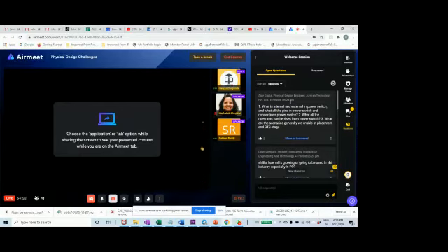So, what are the internal and external power switches, and what are all the pins in a power switch and the connections of the power switch? That is the first part of the question. Okay, let me talk about internal and external power switches. You can have a power supply switch to a part of your logic or to the entire chip, either through an external chip which will have a power switch in it, or you can have internal switches which will be operated through a power gating logic.